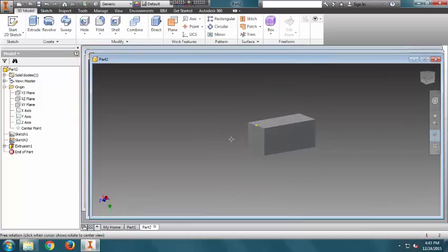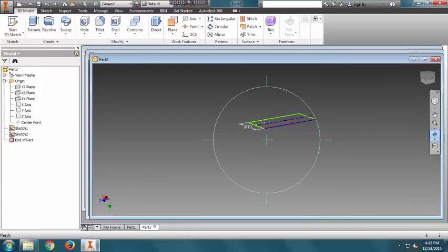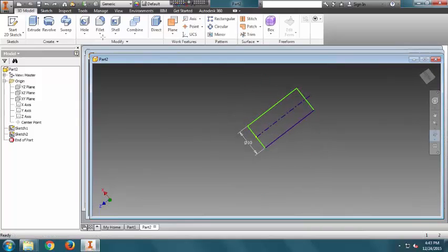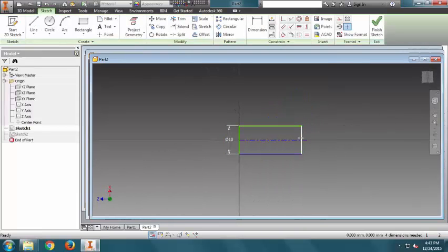So I'll show you how to do a fillet option in a 2D sketch. Select the sketching. Now I want to do a fillet here, so let's select the fillet. Let's click on this line and this line. Give the radius here, and that's the fillet you have. It's the same as doing it in AutoCAD. So let's do the offset, select this and then do the same offset. There you go, you have an offset here.